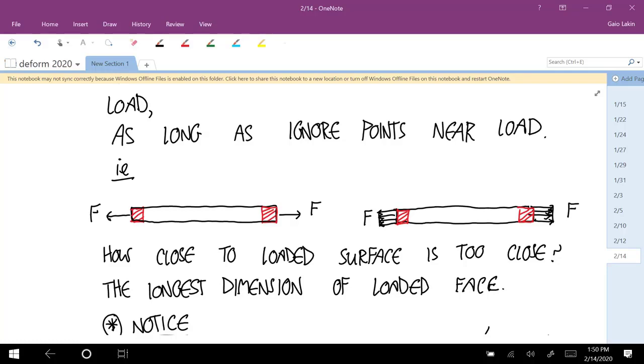And that actually has a practical application in materials that are really brittle. If you have a pure compression fracture of, say, a bone, but it happens in other brittle materials too, what you see always is that, like in car accidents, people's feet hit the front by the pedals, they get compression fractures in their legs. What that looks like is a fracture at 45 degrees, like this, because brittle materials are very bad at handling shear stresses. And so it fails in shear. And if it's going to fail because of shear stresses, it's going to happen on that first face where the shear stress is big enough, and that's at that 45 degrees.